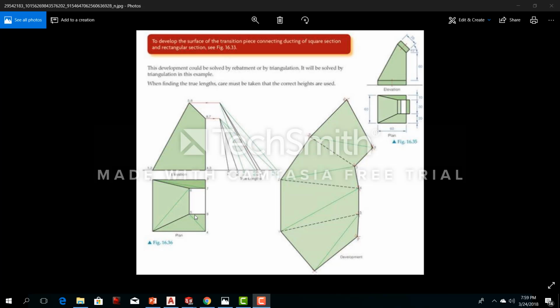They must either both be parallel to the original line, or one line needs to be parallel on the surface, and then the opposite line, both of them will appear skewed off to the side. So because of this, we can say that these two lines are skewed lines, and any surface stretched between two skewed lines is a warped surface. So that's a warped surface, and it's called a hyperbolic paraboloid.